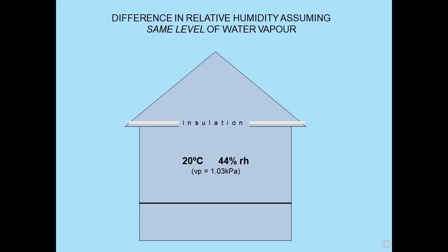So in our hypothetical building, the air is going to move up and down, round and round, and it passes into the subfloor void, and it's cooled to 13 degrees. The relative humidity, in other words our bucket got smaller, now increases to 69%. Indeed, the water vapour goes into the roof where it's really cold, it's a very cold day out, to 9 degrees.